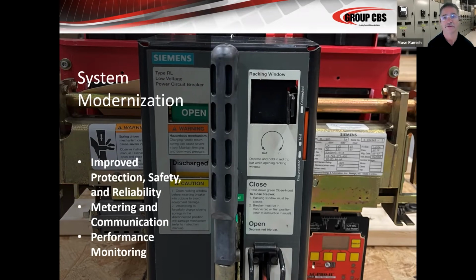NFPA 70B is probably the best example and probably has some of the best references for this periodicity. But in the NFPA 70B, there is a chart, and basically it's a graph where they say the cost of maintenance, the cost of replacement, and those two lines at some point intersect, right? If I could spend a ton of money on maintenance and minimize my failures, or I can spend no money on maintenance and my cost to repair and replace will go up. And there's a point where those two intersect. And that's maybe more of a financial decision. But, once again, those things are all kind of driven together. And once again, plenty of references out there.